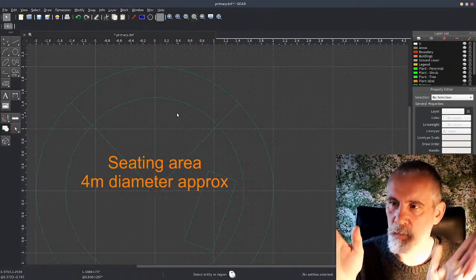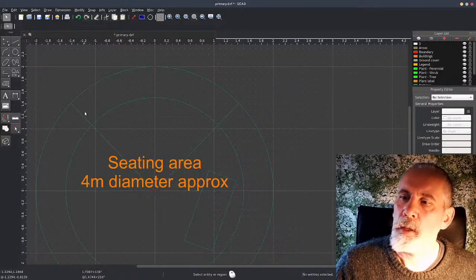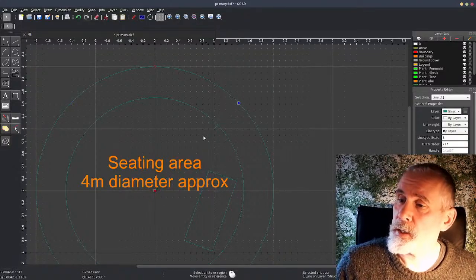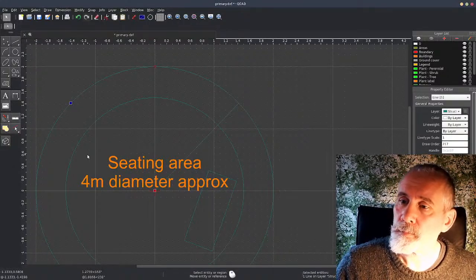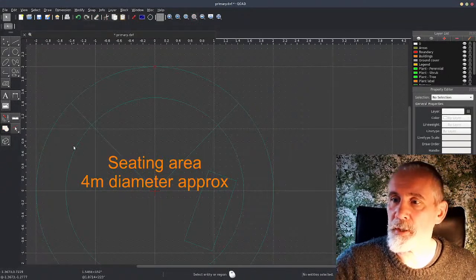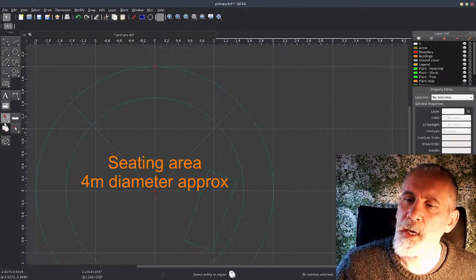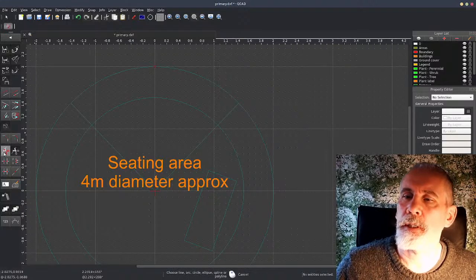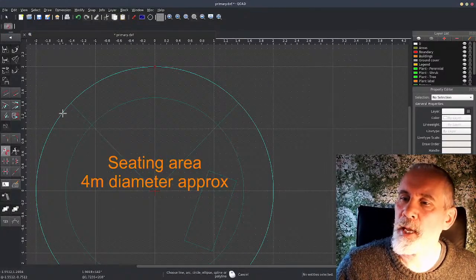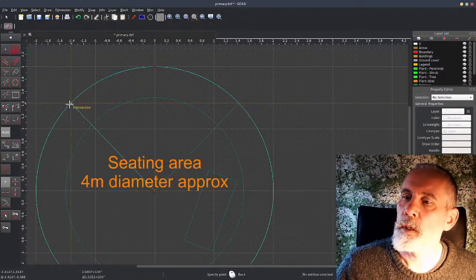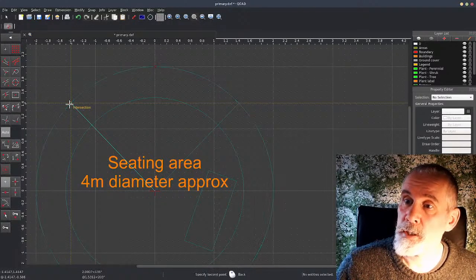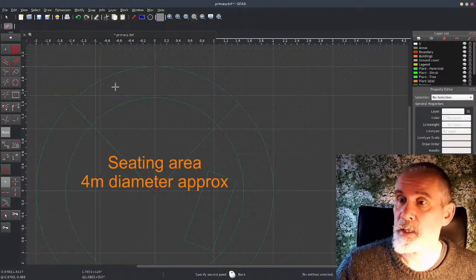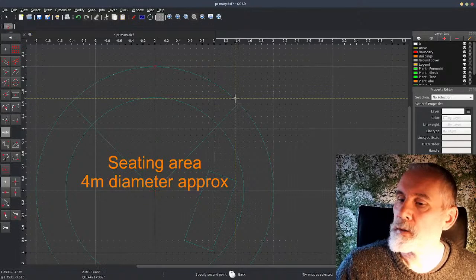Now this is one of the most important things, how to cut the circles. So I've got to get a wedge and cut that wedge out. And these are guides. These two lines, I'll get rid of them eventually. So the first thing I'll do is cut the outer circle. It's a modification tool, and there's a pair of scissors, and it's a divide tool. I select the outside circle first of all, click, and it says intersection, so that's where I know it's intersecting. And has that worked?